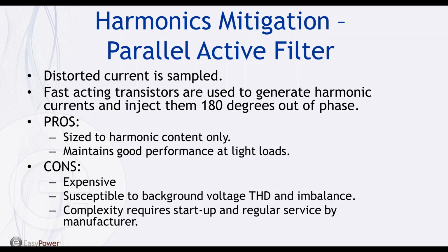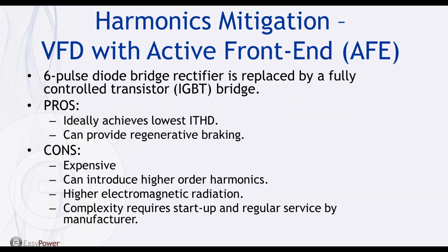The cons of using these filters are they're expensive, they're susceptible to background voltage total harmonic distortion and imbalance. Also, the complexity requires startup and regular service by the manufacturer.